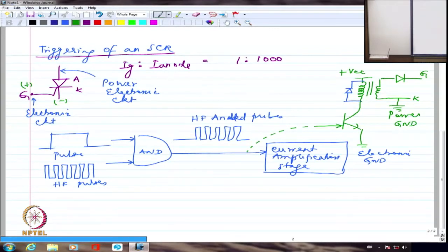because there, if you give a base pulse, the base pulse has to be in high condition continuously for the device to conduct. If the base pulse is not in high condition, it will come from on state to off state, and we don't want, in all probability, our device to go from on state to off state. Most of the times we fire it with multiple pulses, because by chance if it doesn't fire here, it can at least fire here. By chance if it misses these two, it can at least fire in the third, and so on.